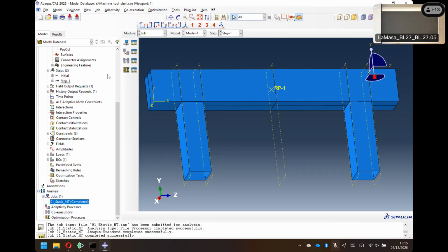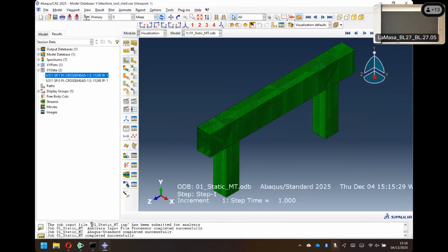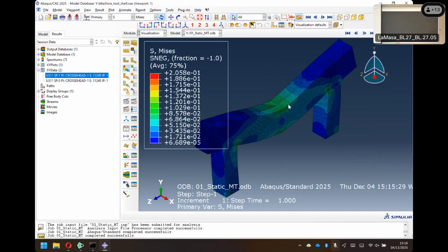It did compute, it did use all the 5 section points. It's not doing additional calculations now. It had computed all the stress in the 5 points, but in the end, it just saves the first and the last. Why this? Because if you have to save everything, the output file becomes very large. Anyway, again, exactly the same results.